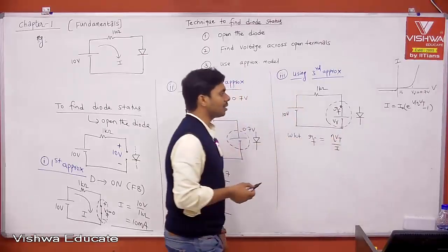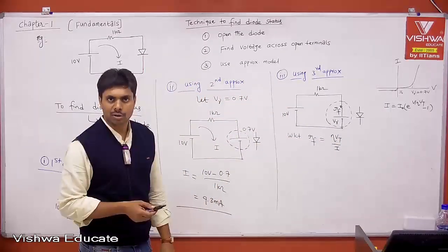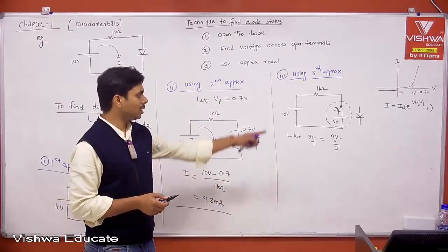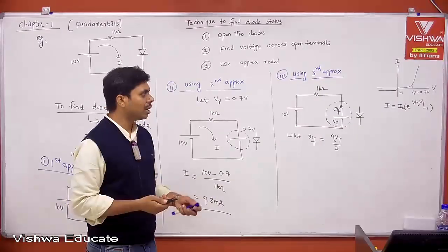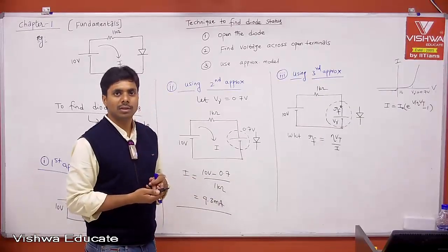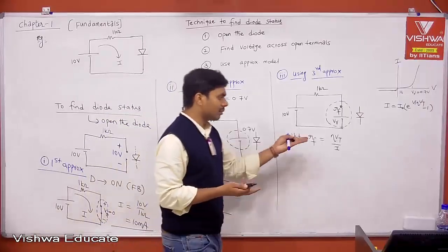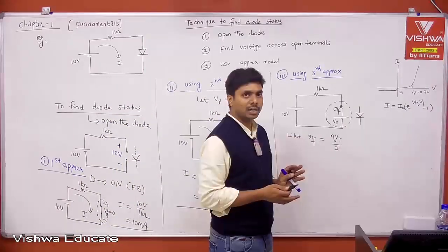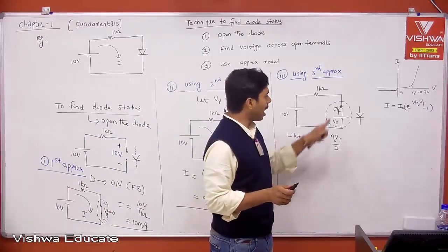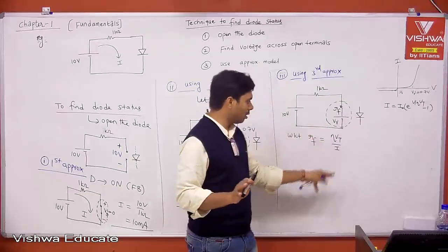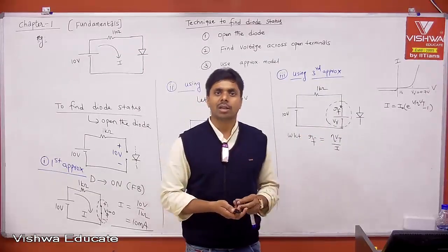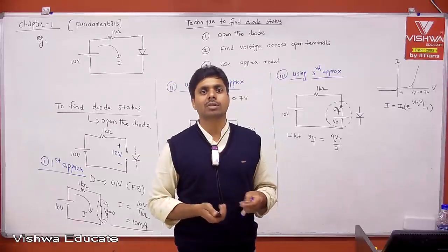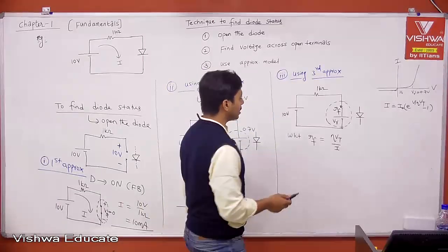Therefore, when V gamma is 0.7, that is definitely a silicon PN junction diode. For a silicon PN junction diode, what is eta? Eta is approximately equal to 2. Because nothing is given, we need to take it on our own. If nothing is given, you can take eta as 2. But remember, in the problem statement RF will be given straightforward, so there is no need to do all these calculations. If it is given, use it directly. If not, we need to calculate it based on the operating point. Okay, let's see.